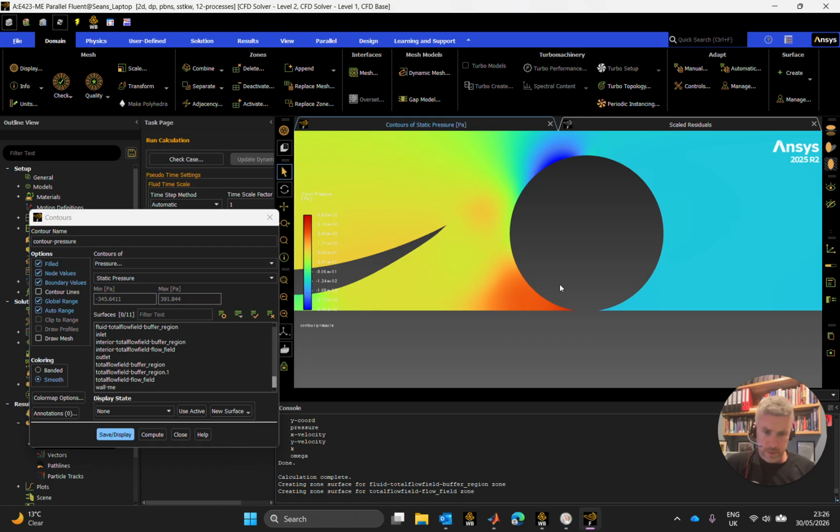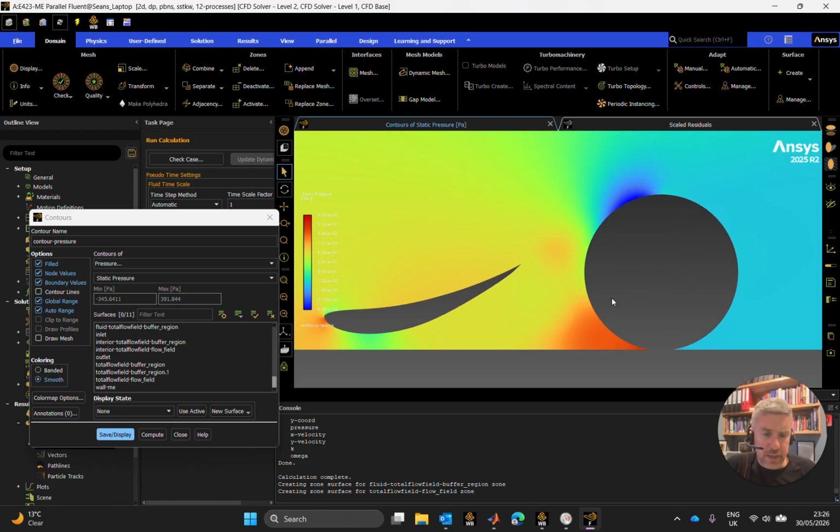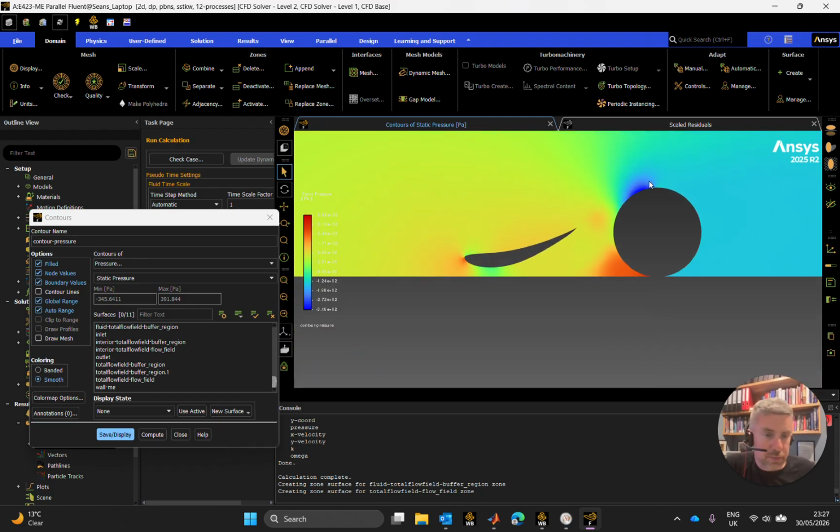In 3D, that air is going to be coming out by the side. We'll be washing out, we'll be washing in, we'll be tumbling it around. This is really just to give some sort of an indication of the air coming off of that airfoil, the treatment onto this, from a 2D perspective, which is always going to be very limited. But noticeably enough, we could see a low pressure region here over the top, which makes sense because we have accelerated flow, but it also means that the wheel is contributing to lifting the car off of the road, which needs to be dealt with.